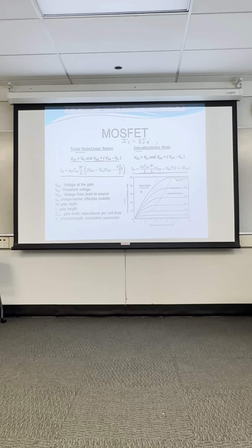There's only one result for this I sub C, and that's what the inventors of the BJT transistors came across, that out of thousands of transistors, this equation always held. I sub C was beta times I sub B. Now in MOSFET, these are the two drain equations, basically similar to I sub C.